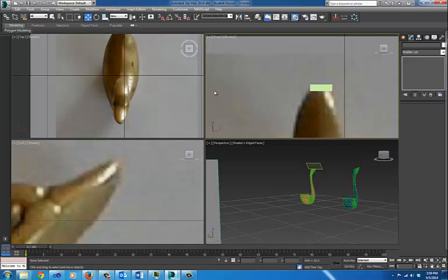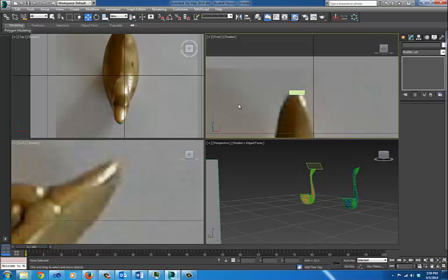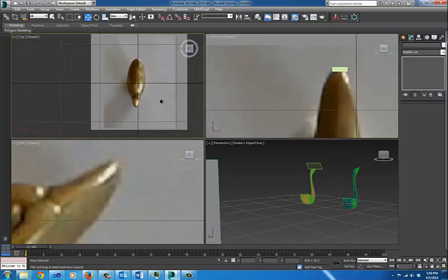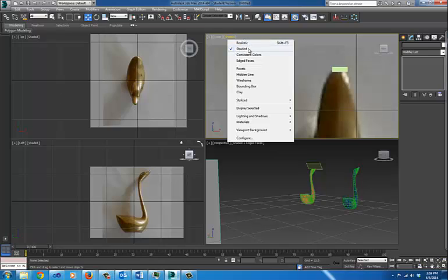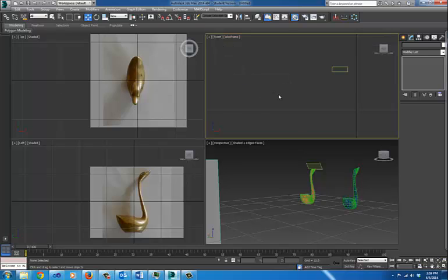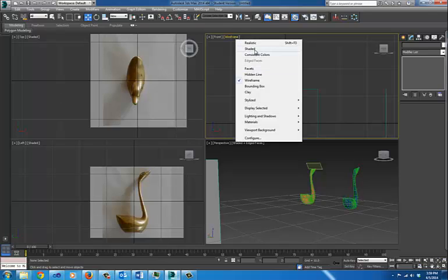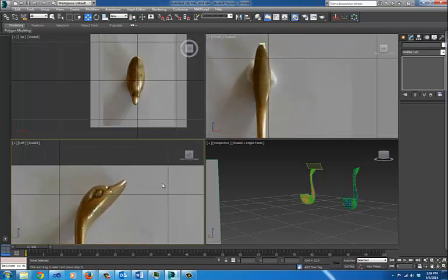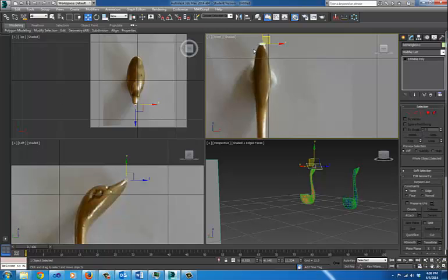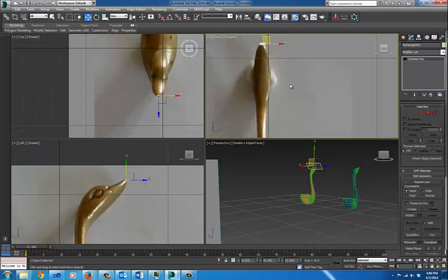Now just a quick overview about how you would be able to see the pictures on the planes in the three-dimensional virtual studio that you set up. You need to click on the viewport options and check the shaded option. Otherwise, your orthographic views are going to be wireframe views, and they're not going to be much use. So now I have my beginning box, which is effectively the beginning of my model.